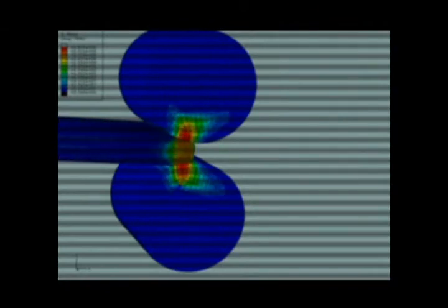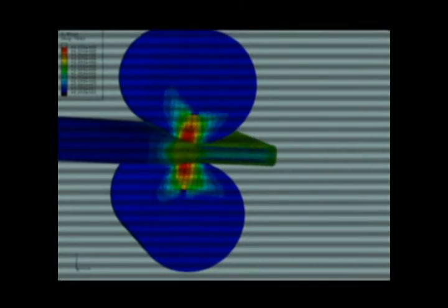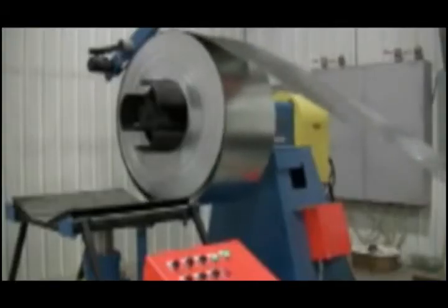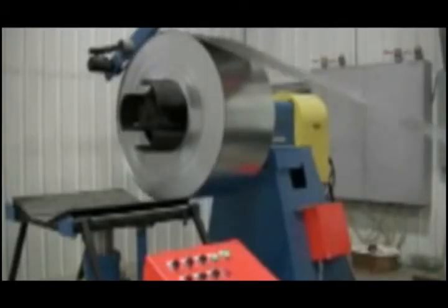This is the second video, where another version of the rolling is shown, a very industrial version of the rolling which is carried out locally here. Here the hot worked sheet goes through what is in fact a 3 high rolling mill. So, it is a reversing kind of mill, you can see here.